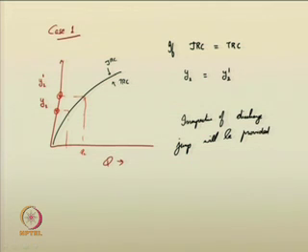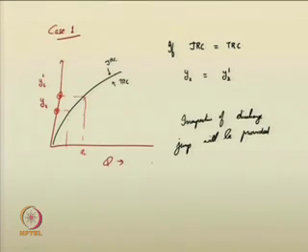You know that at the source of the jump, the pre jump depth y 1, say from the overflow spillway, is a fixed, specific depth. Whatever discharge comes from the spillway, even if it is reduced, it does not matter, the jump will be provided at the same location.